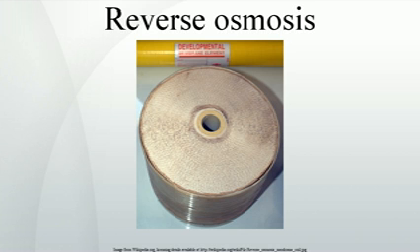Only a part of the saline feed water pumped into the membrane assembly passes through the membrane with the salt removed. The remaining concentrate flow passes along the saline side of the membrane to flush away the concentrated salt solution. The percentage of desalinated water produced versus the saline water feed flow is known as the recovery ratio. This varies with the salinity of the feed water and the system design parameters, typically 20% for small seawater systems, 40% for larger seawater systems, and 80% for brackish water. The concentrate flow is typically only 3 bar/50 psi less than the feed pressure, and thus still carries much of the high-pressure pump input energy.